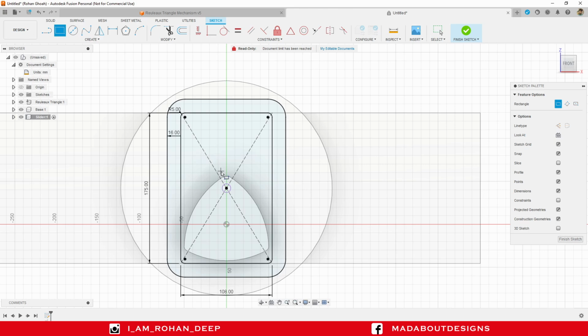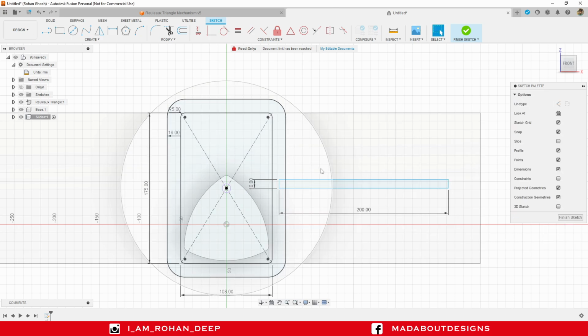Select the first point horizontally aligned with this center, here in between these two lines, and give it a dimension of 200 by 10 mm. Press enter. Change it to 5 mm.